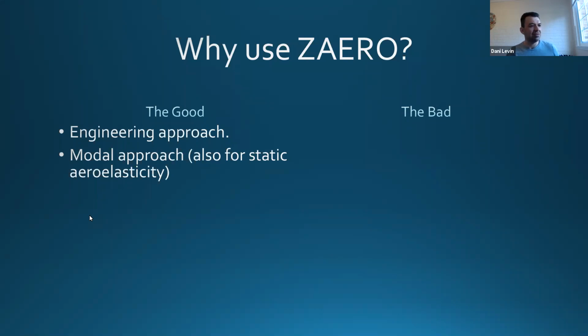Sorry. Yeah, so if I'm using the modal approach, if I'm just describing my structure as a combination of linear natural modes, in what circumstances do I need to use more modes? With flutter solution or for static solution? For static solutions. That's right. Why? Because usually flutter is fluttering in one specific mode. So for dynamic results, you usually flutter or dynamically accelerate at several modes, one or more. And for static, you need more modes to do a general combination of motion.